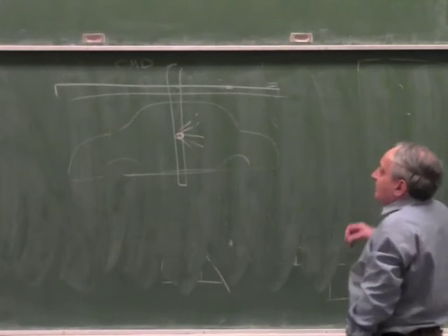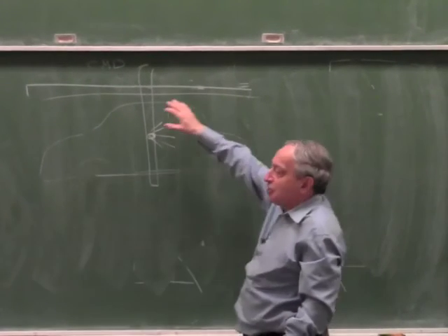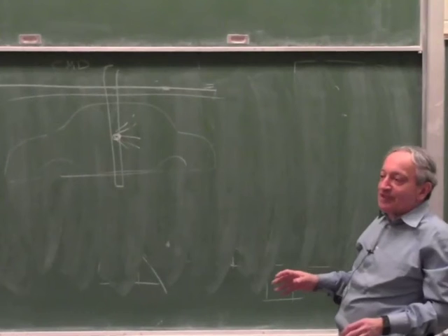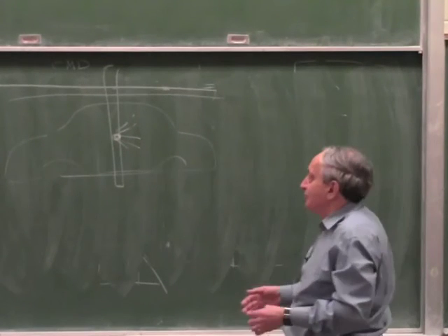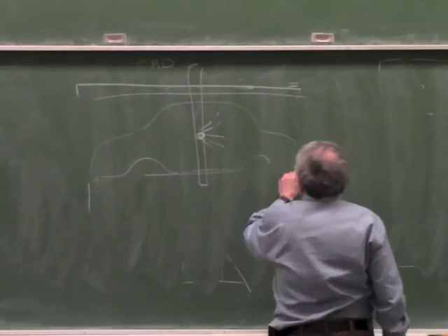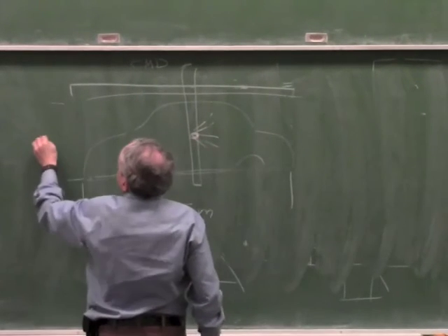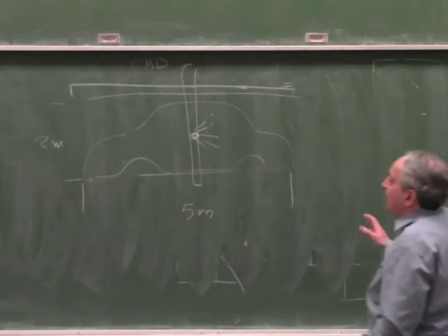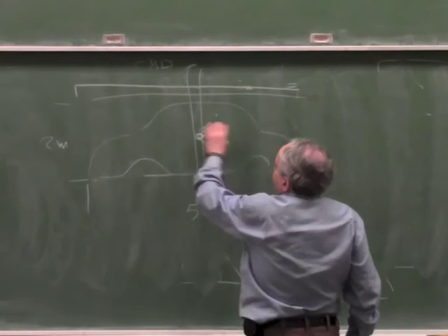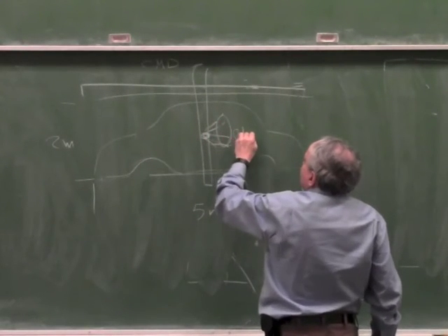And I have a servo system because I program this robot with the shape of the car, and it has to paint the car. So I have to specify the servo system components to do that. So let's say the car is 5 meters by 2 meters, could be any shape, and let's say that each pass of the robot is 0.1 meter wide.